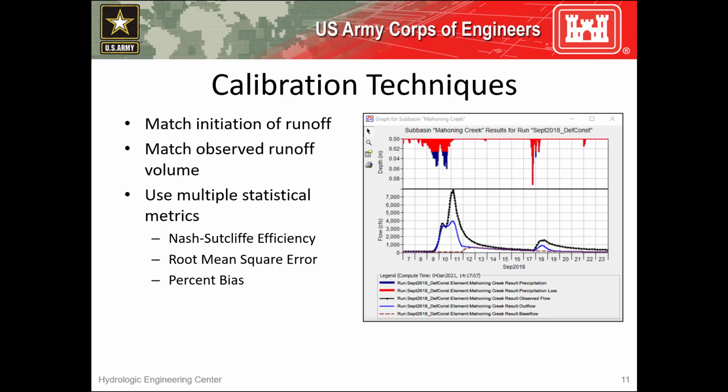As always, when calibrating, use multiple statistical metrics like Nash Sutcliffe efficiency and percent bias to measure model performance as they compare your results from different perspectives and are better than the old eyeball test.